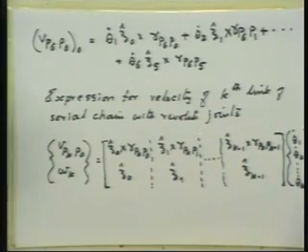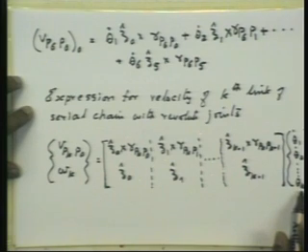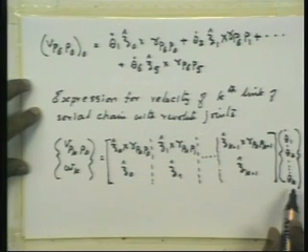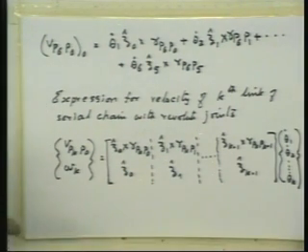This gives both the forward and inverse relationship that we want. That is, this expresses the velocity of the kth link in terms of the joint variable derivatives up to the kth link, up to the kth joint, right. Rotation you give to the later joints does not affect the kth link in a serial chain. In a parallel chain it is different.